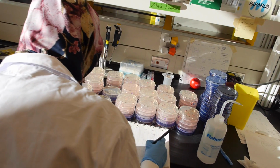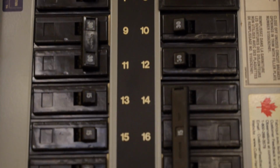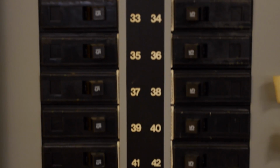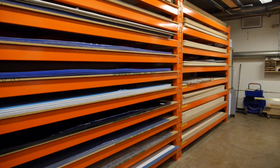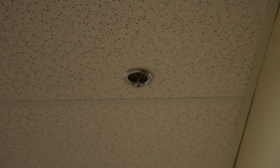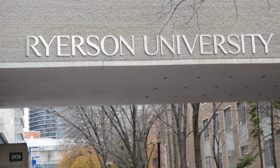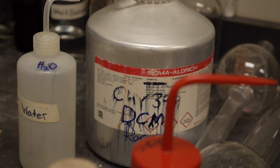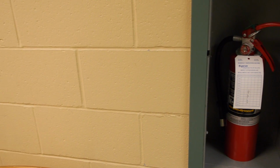Depending on where you work, please maintain full access to all control panels so that no material or equipment will slow down the shutting down of power during an emergency. Also, when stacking materials, be aware of the overhead clearance so that you're not blocking any sprinklers. Always try to practice good workplace housekeeping, as clutter contributes to fire hazards by providing fuel and preventing access to fire exits and emergency equipment.